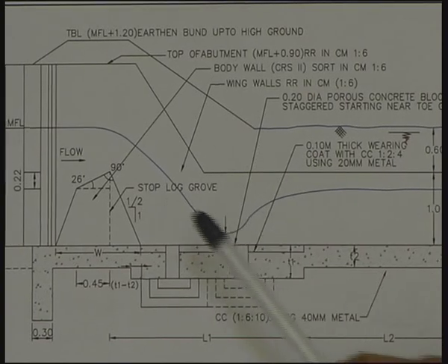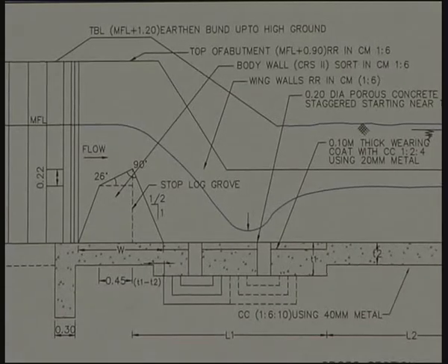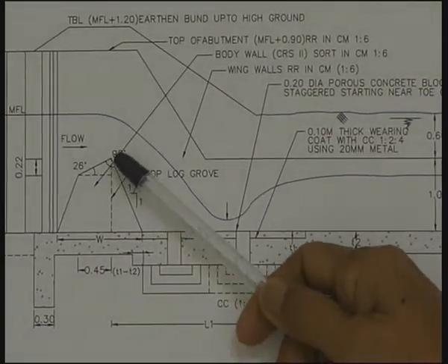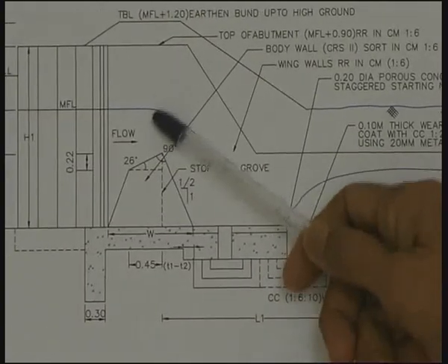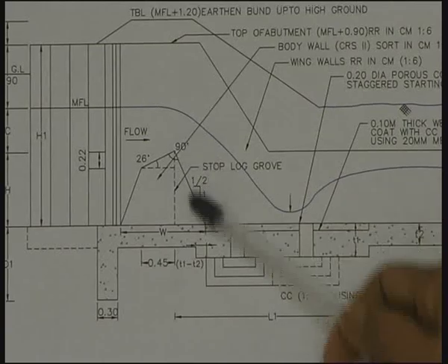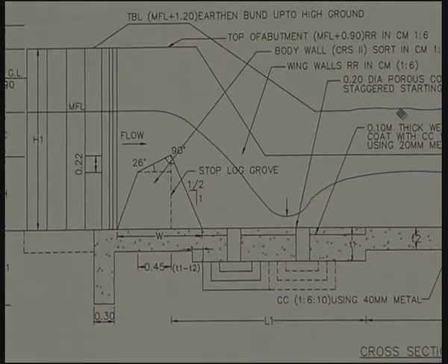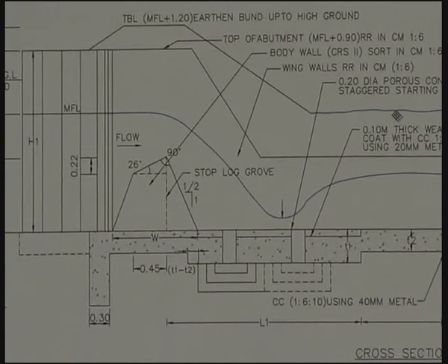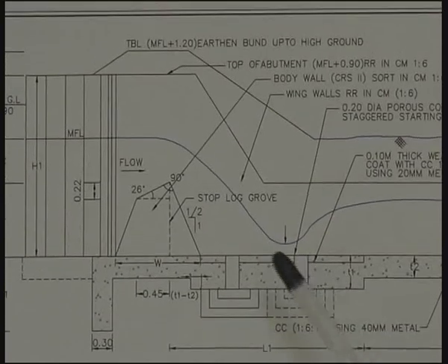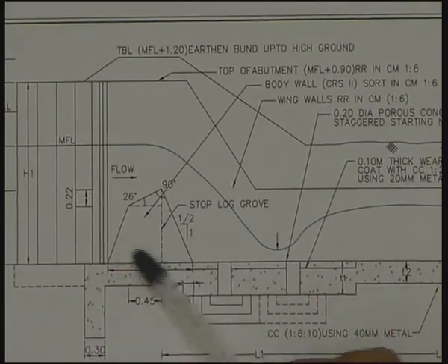A greater quantity can be discharged when there is a high coefficient weir design. In the case of a low coefficient weir, for the same discharge, a greater depth of flow would be needed. So this is optimization on the design of the body wall of the weir to have the maximum coefficient of discharge, and at the same time to facilitate the rural labor to construct it easily.